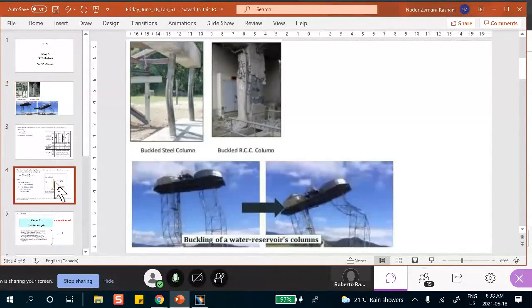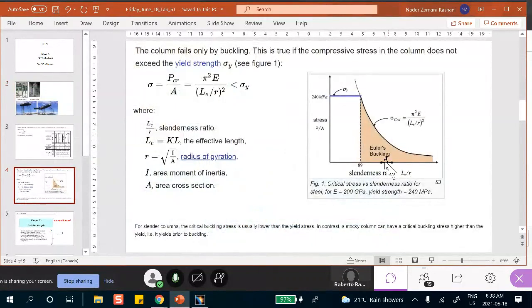But if the beam is slender, very tall and thin, it really has nothing to do with the length or height or cross section alone. It is the ratio of two things. If the part is very slender, notice that it buckles at a much lower load. This is a stress, but you can still multiply it by A and get your load. So be careful.